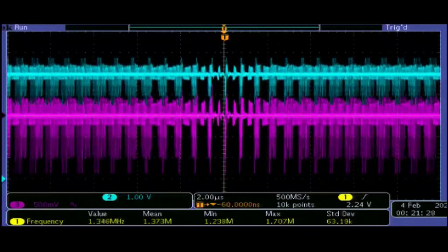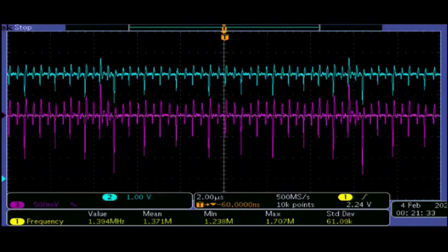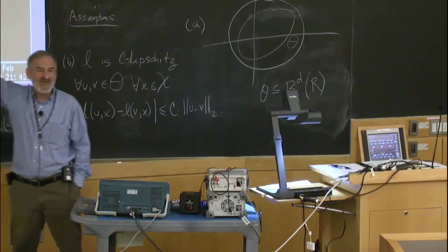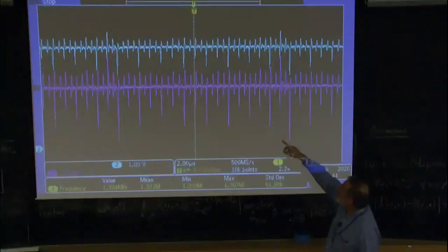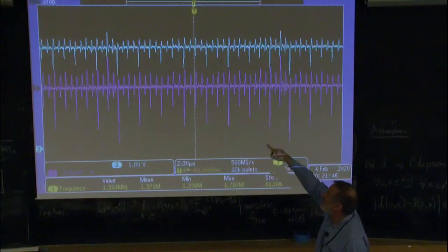The blue up there, and I'm just going to stop it because it's a little easier to see. The blue, this is 1 volt per division, 1, 2, 3, 4. That's the 5-volt supply at 1 volt per division. Those spikes, those are the things I don't want. Those aren't supposed to be there. That's noise. And they're huge. I mean, they're basically almost a volt peak to peak.